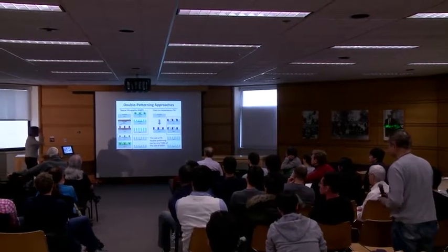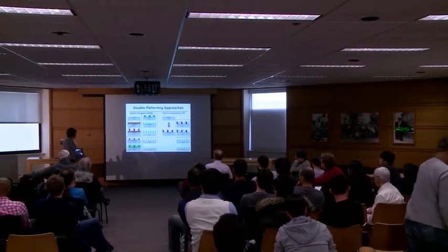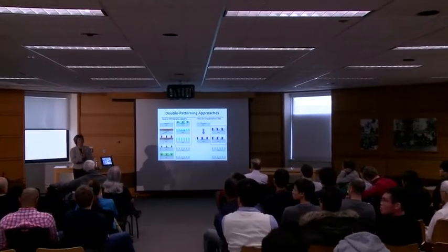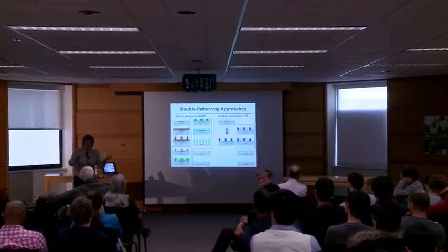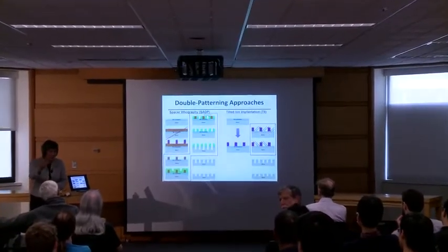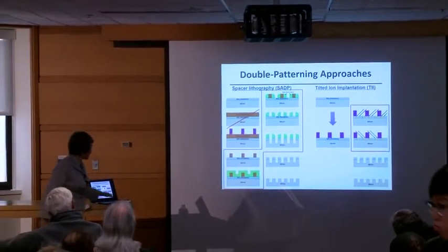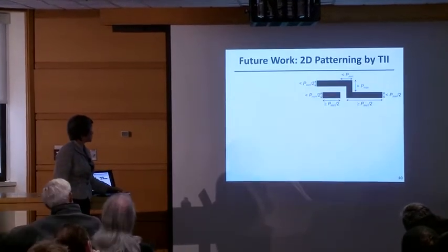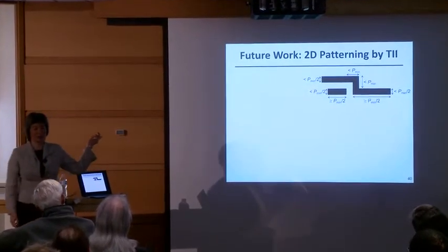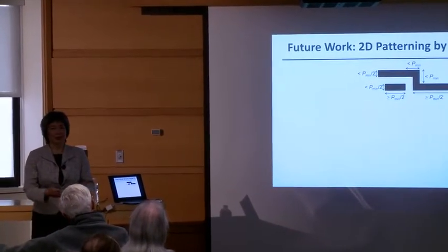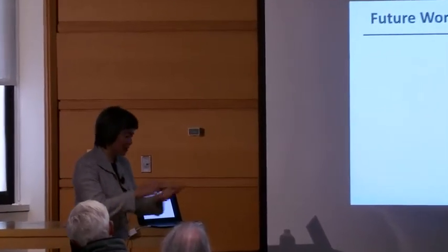Yes. Okay. So today, with self-aligned double patterning, multiple lithography, multiple masks are already used to define a single layer. So there already are programs to automatically partition the pattern across multiple masks. So I think that should be relatively straightforward to do with this technique. In fact, spacer lithography is more complicated because the spacers, if you look in plan view, wrap around the ends of those mandrels.